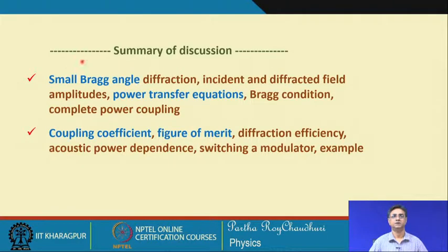So, we discussed small Bragg angle diffraction, and looked at the power transfer equations and the condition for complete transfer of power, that is the Bragg condition. We also discussed non-Bragg condition power transfer, then the coupling coefficient, including the definition of the figure of merit, and then the diffraction efficiency and the acoustic power requirement for switching a modulator, and we also discussed a numerical example. Thank you very much.